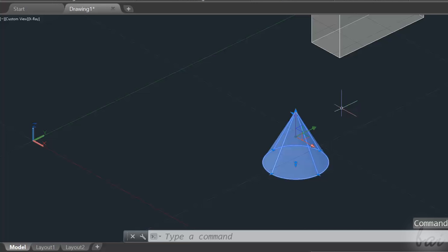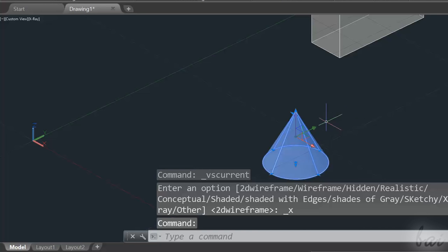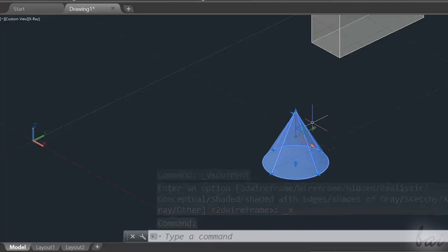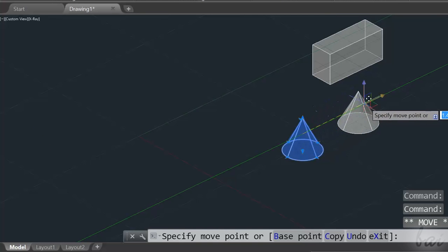Apart from the nodes, you can also use the object gizmo that appears when you use any 3D view, so any except the 2D wireframe one. This gizmo is associated to the current object selected on your workspace, and is used to edit your object precisely, according to the three main X, Y, and Z axes seen.